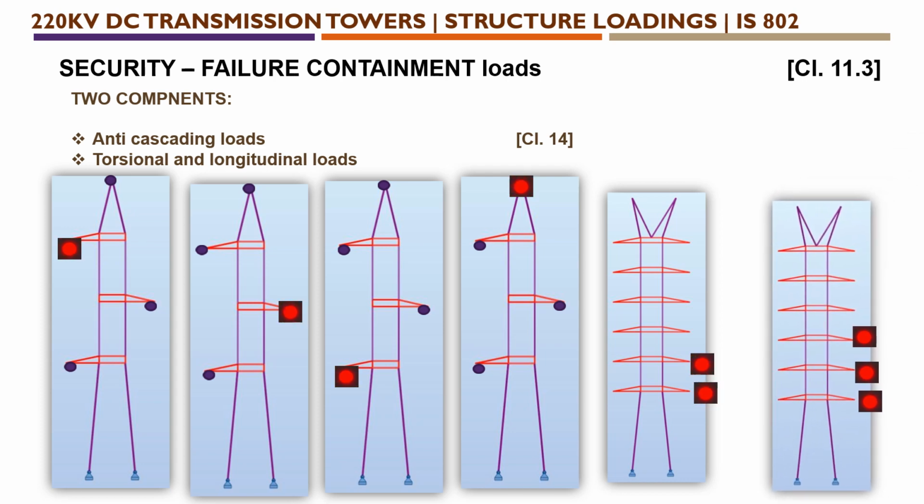Similarly for another case on the right hand side, you can see three phases on one side are failure, all the other spans are to be considered as intact spans. So these are the major cases we need to consider for torsional and longitudinal loads.